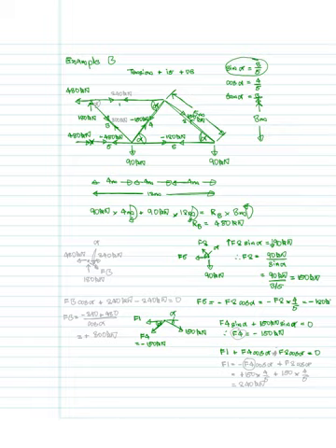So we're just obeying the convention of tension is positive, so all our arrows have been drawn in the tension direction, so the negative signs of compression and tension will come out in the wash. So from there we get F1 is equal to negative F4 cosine alpha minus F2 cosine alpha.